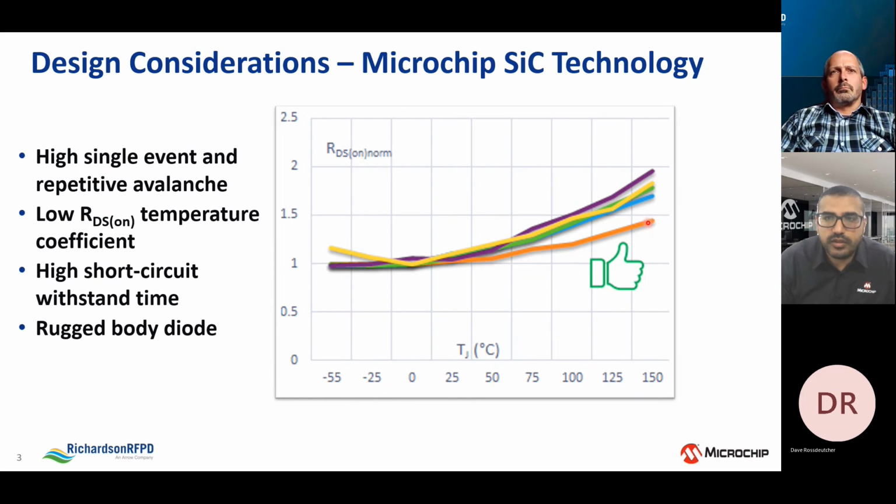And then a rugged body diode. We do have a rugged and stable body diode. There's no issues with stacking faults or any degradation in the forward voltage or RDS on. And this has been verified by independent third-party testing.